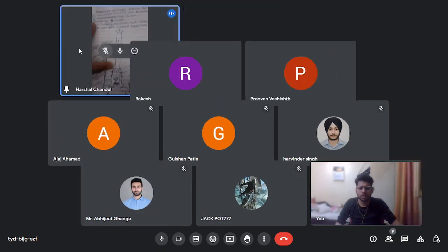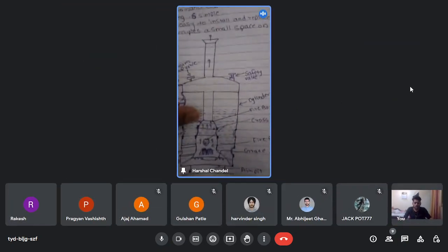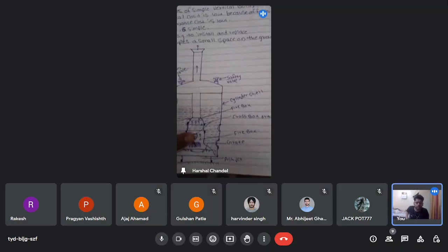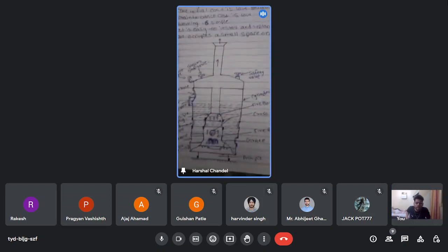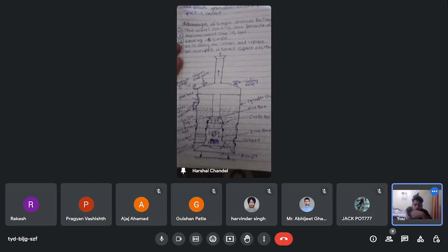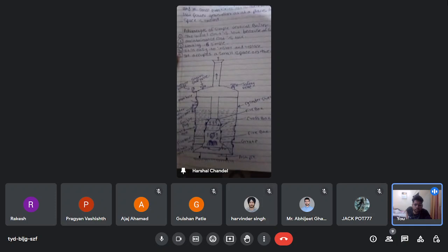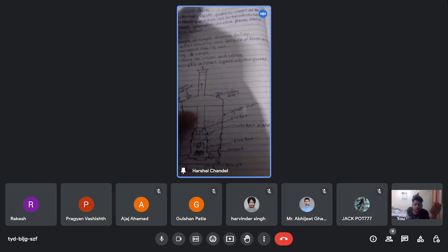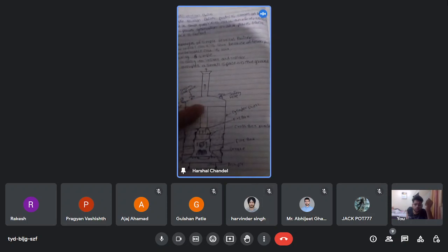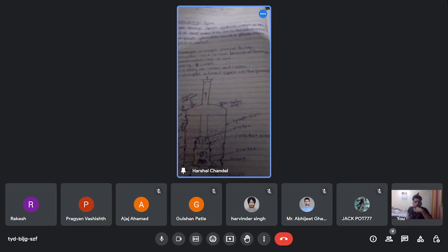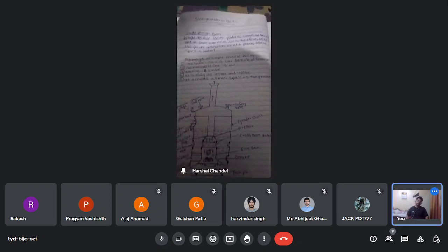So here is the fusible plug exactly. You see, it is on the furnace plate. Here is the combustion, and here is the fusible plug. It is a steam drum. Here is all the water, and here you have the steam space. So whenever the water goes down, this fusible plug will melt, and it will extinguish the fire. Oh, as simple as that.